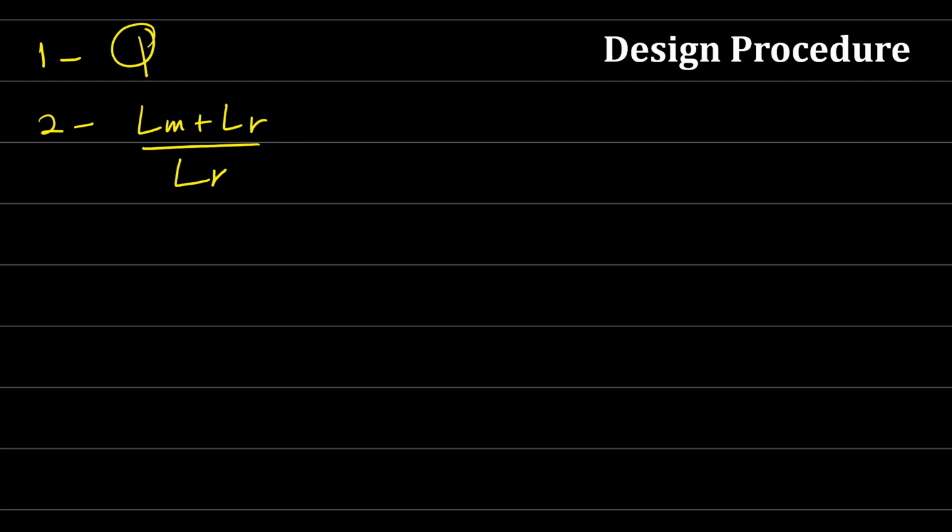For small M values, if the magnetizing inductance and the resonant inductance are very close to each other, which means M is very small, we can achieve higher boost gain, and a small M value can also accomplish more flexible regulation since a narrower range of frequency modulation is needed. But small M at fixed Q and omega naught causes smaller magnetizing inductance, and then we have higher magnetizing ripple, high circulating current and conduction losses.